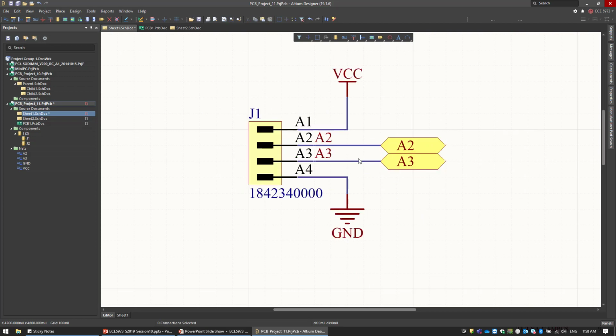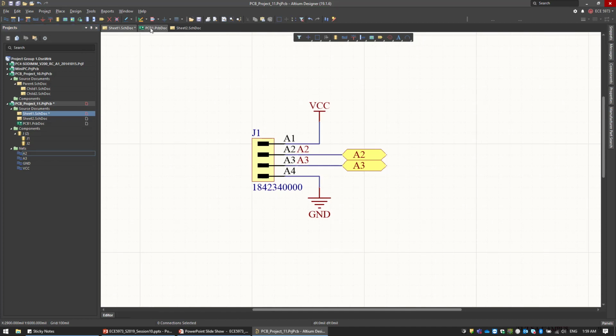This will tell you the priority Altium Designer uses to name the nets. So basically, if you have a board, Altium Designer will automatically name the nets based on the default naming scheme. Now, if you have a net label placed over the net, you are forcing the software to use your net label name rather than using the default naming scheme. And this is one of the important points. So now you can see a more meaningful name for you to understand what's going on in this net.